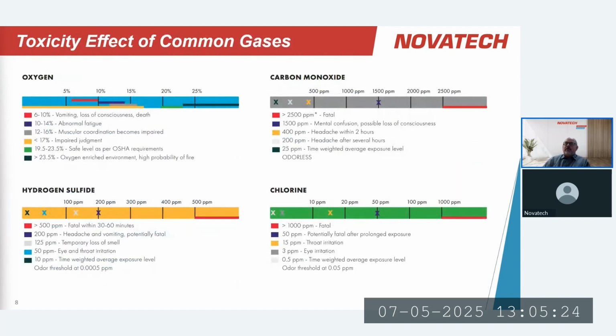It's important to think about toxicity and its effect on people because often, especially when we're talking about hydrocarbon industries, our focus is primarily on flammable gases. And we think of that hazard first and foremost. But we do have to pause and think a little bit about what else might be present. As an example, if you're dealing with some kind of sample, a crude, for example, crude oil, or a sour gas of some kind, the toxicity effects of the H2S, which may be present in that sample, will be a problem long before we reach flammability limits.